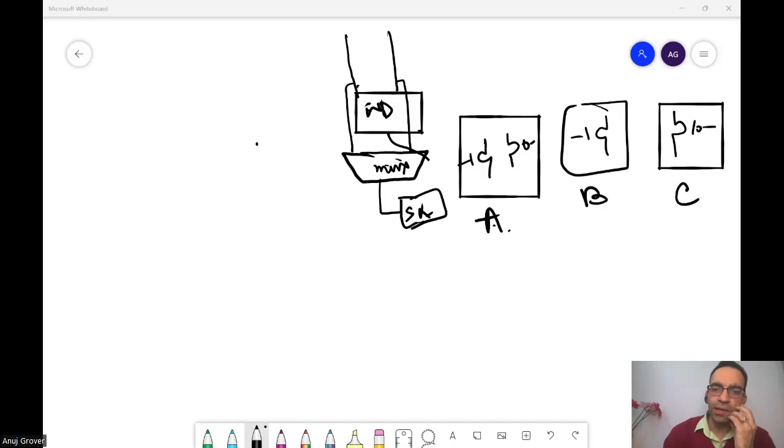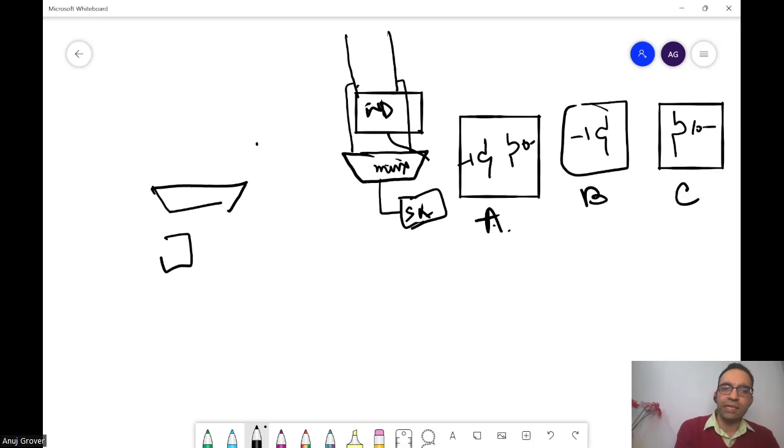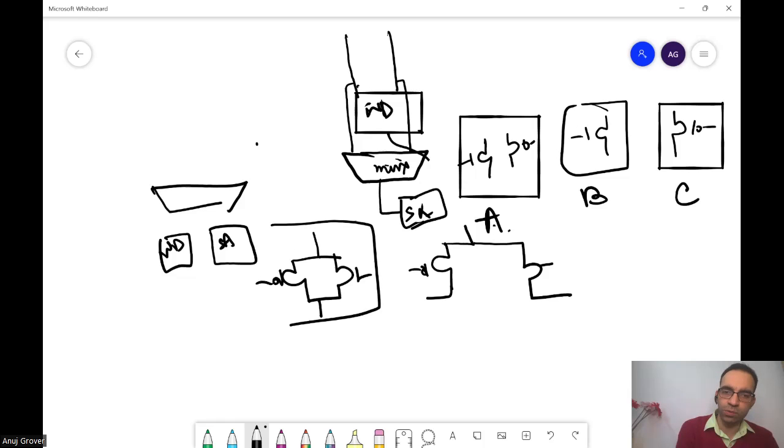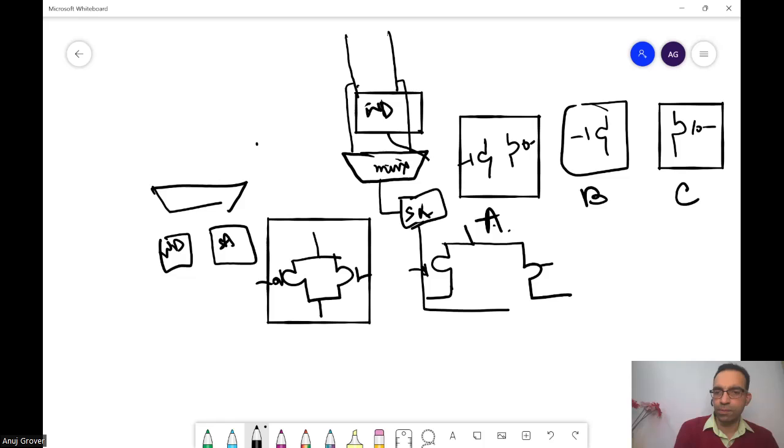So tell me one thing. Let us say another case where there was this mux, and both the write driver and the SA were here. Do you now want to design a transmission gate like this, or would you want to keep the transmission gate like this? It's not really a transmission gate here. So there are again two configurations possible. Which one would you prefer?